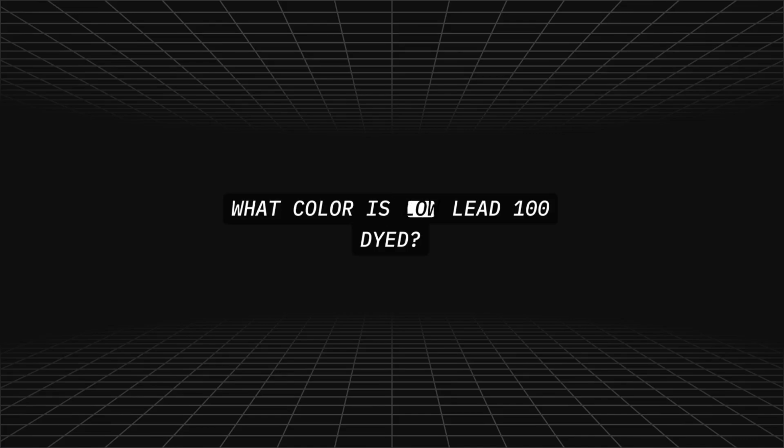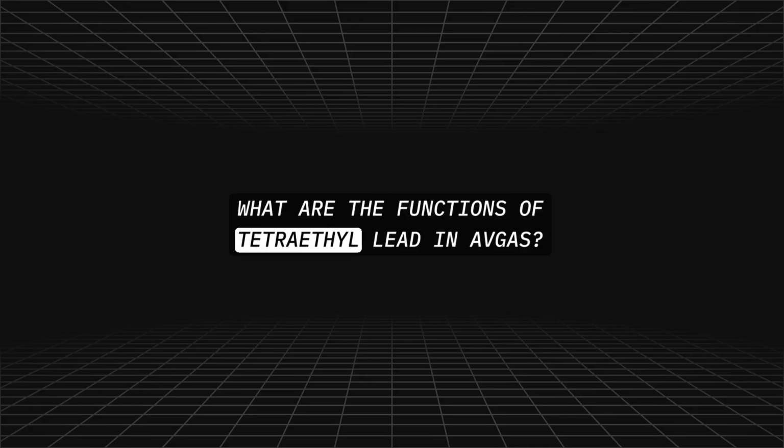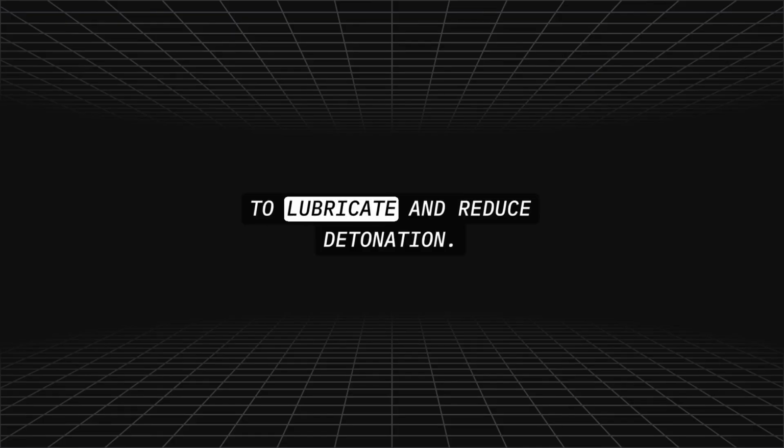What color is low lead 100 dyed? Blue. What are the functions of tetraethyl lead in avgas? To lubricate and reduce detonation.